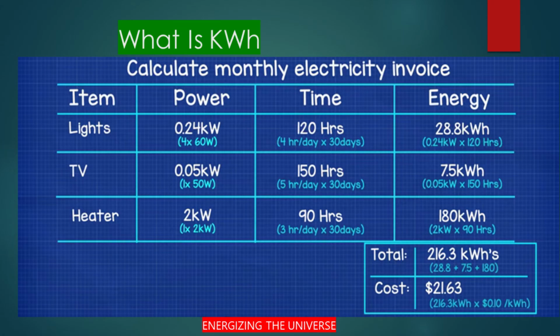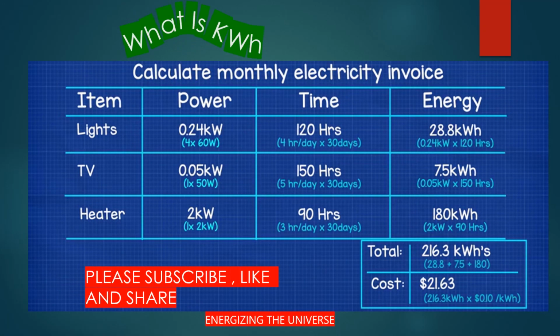On concluding about calculating electricity consumption for our month, you need to organize the items used in the building and note down their power. Then we need to calculate how many hours per month each will be switched on. Then we can calculate the electricity consumption for each item using the energy equals power times time formula. Don't forget, there will likely be other costs on the supplier's invoice, things like tax, etc.